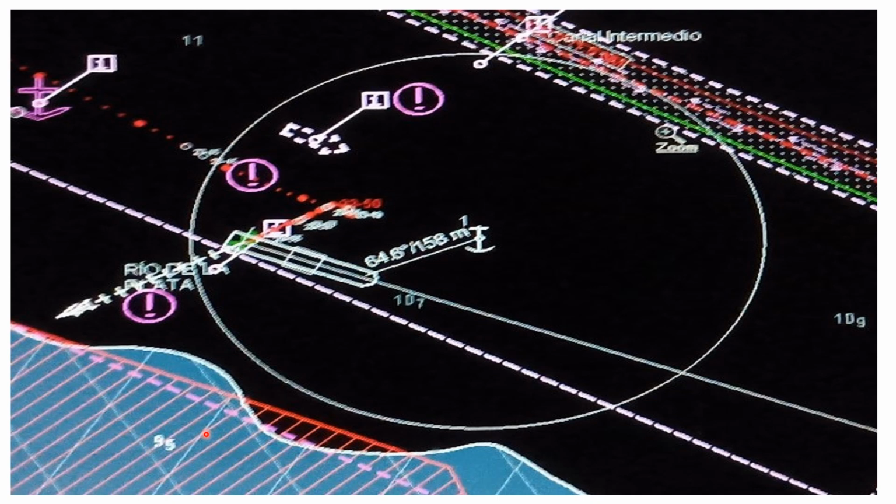The swinging circle of your vessel is this circle here. That means if your vessel is not drifting, it should stay inside this circle. So in case you notice the vessel going outside of this circle, that means your anchor is dragging.